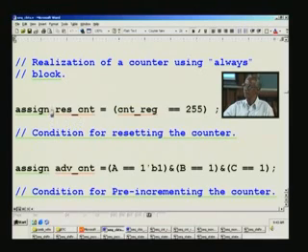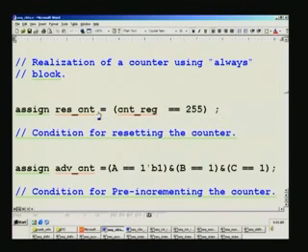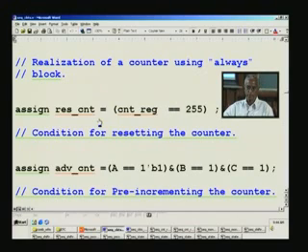So it is a very misleading conception to simulate and jump to the conclusion that you have achieved gigahertz operation. For example, it depends upon the FPGA that you choose. There are wide varieties of FPGAs and different vendors, and in each vendor there are many categories, and even in one specific type number of an FPGA, you have 2, 3 or 4 varieties of speeds. So depending upon the actual device, your speed will depend upon that.